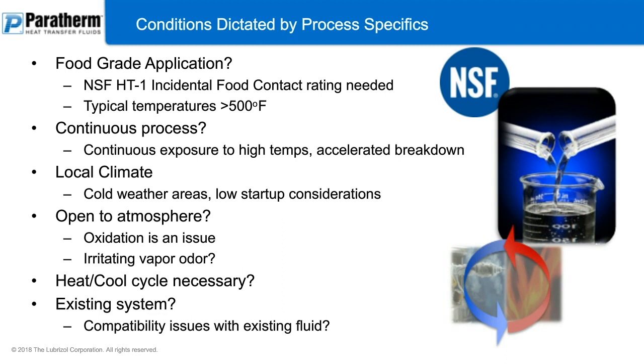Is this a continuous process? That's the next condition that you should look at. In a continuous process, there's going to be long-term exposure to higher temperatures. There's going to be perhaps an accelerated breakdown. And what you're really going to need to do with a continuous process is make sure you have a fluid monitoring system or a great relationship with your supplier to monitor the fluid so that you don't have unexpected failure, degradation, or maintenance practices that come up because of that.